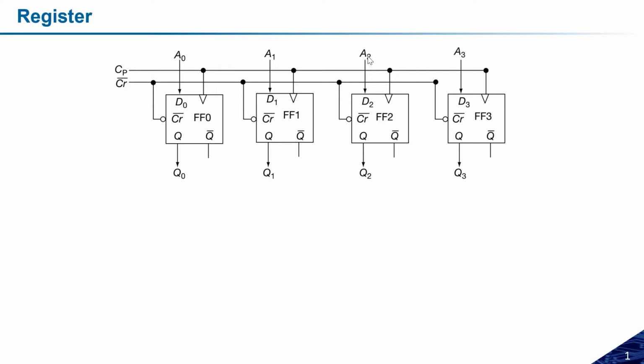So when you have to store data, in that case the RS flip-flop and the D flip-flop are useful, because they have the capability to just pass the data along. If you look at the D flip-flop, whatever input I am giving, if the clock is executed, it will pass the same logic to the output. And if the clock is not executed, it will hold the data. It is not going to perform anything. So the D flip-flop and the RS flip-flop can be utilized to hold the data. See, all the flip-flops can hold the data.